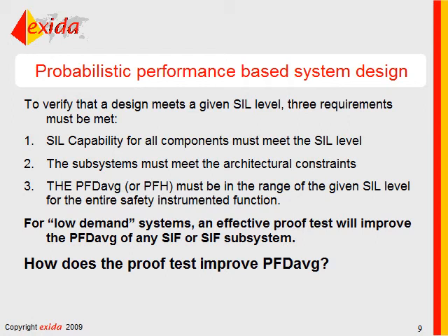First of all, the individual components or equipment items need to have a certain SIL capability or systematic capability, which basically means that the products are either IEC 61508 certified, or the end user has sufficient documentation to prove that there is adequate proven in use experience with these components, that therefore there are no systematic problems in the product. So that's number one.